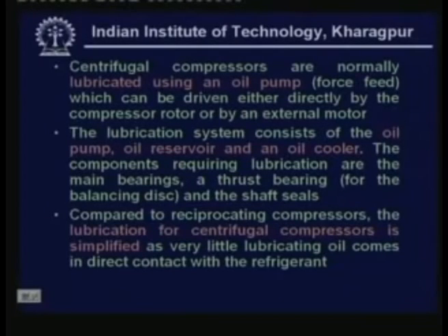However, compared to reciprocating compressors, the lubrication for centrifugal compressors is simplified, as very little lubricating oil comes in direct contact with the refrigerant. So, you find that the design of the lubricant system is not as complicated as in the case of reciprocating compressors, because normally they do not get mixed in the case of centrifugal compressors.